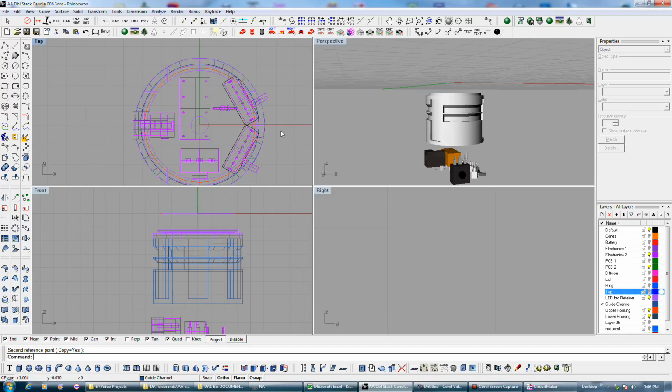So if I am going to incorporate this relay idea, I've either got to go to a different relay or mount this relay off board. In other words, it can't be on the circuit board. I can just solder some wires to it. Again, it's a prototype, so it's no big deal. Because I can get a smaller relay that's about half that size, but I'd have to order it.